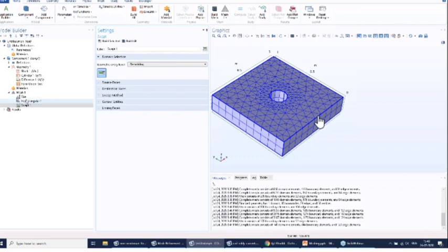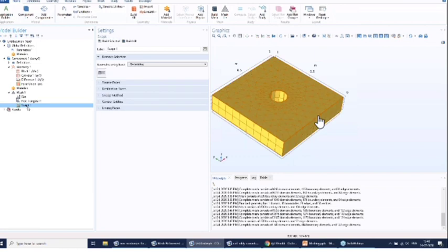So first you have to mesh the top surface and then you do the swept, because swept you have to do in the third direction. It's not like it will create swept for every case. So you need to have a regular kind of geometry to create those swept operations.